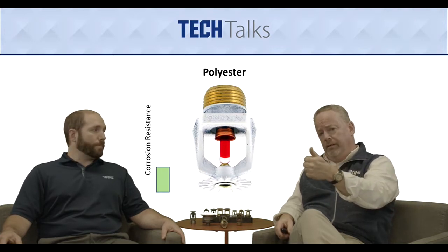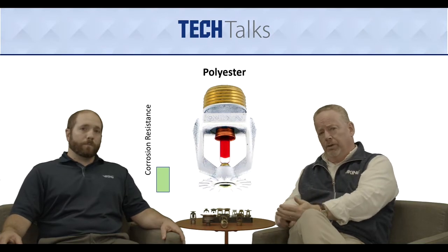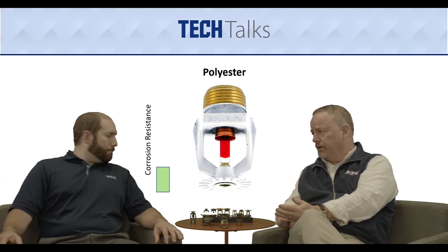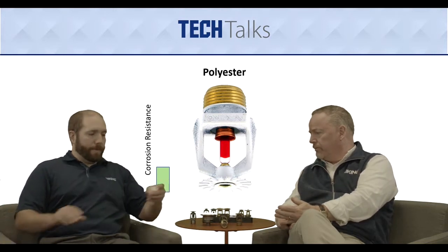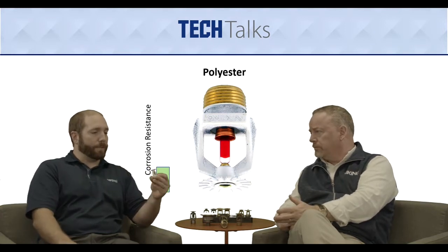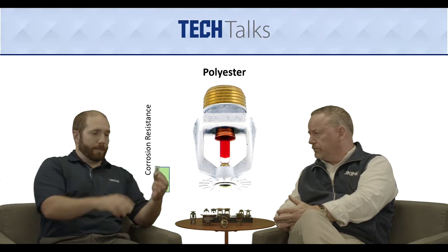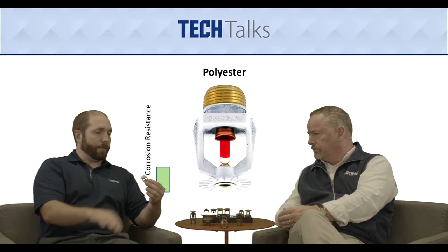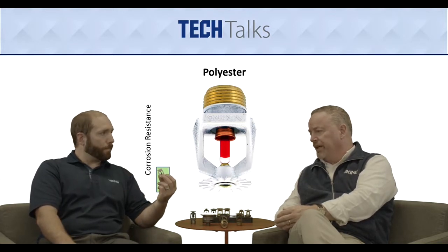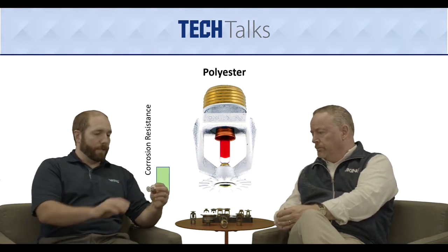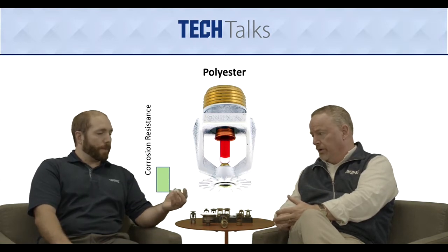So we're looking at the deflector, and we're not looking at the screw though, right? Or does the screw get coated as well? No, it doesn't actually. I have an example here in an XT1 sprinkler, but that little pintle screw holding the glass bulb is not coated. The deflector on this XT1 sprinkler, a BK3021, is stainless steel, but it gets a poly coating. Everything else did not. The pip cap's just stainless steel, the screw is brass, and the waterway also is not coated.